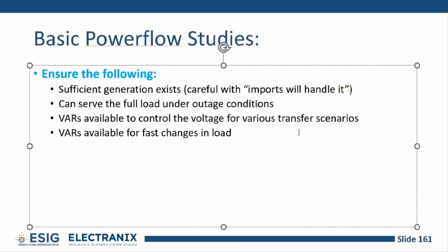We're used to things like duck curves or morning peak and afternoon or evening peak, smooth load curves that look like this. We're not so much used to load coming and going extremely quickly in really large quantities. So if you have 5,000 megawatts of load that can just essentially disappear and then come back at any time of the day, as many times as they want, now you potentially have a dynamic VAR problem, right?